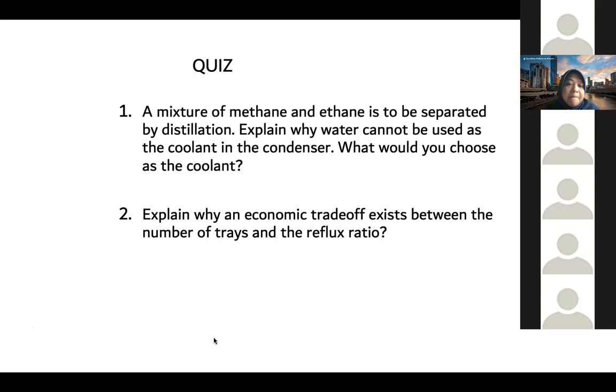For the number of trays, as the n increases, the capital costs will also increase as we need to install more trays. Whereas for the reflux ratio, if it increases, the operating cost for the condenser will increase.